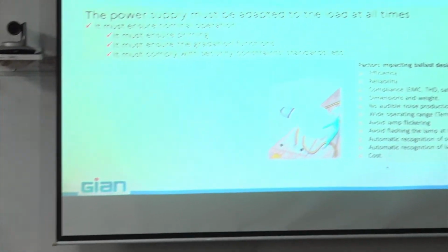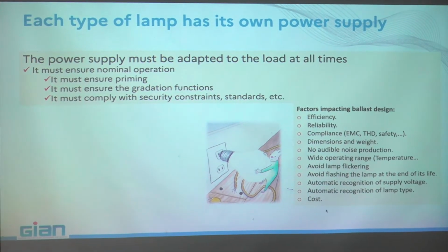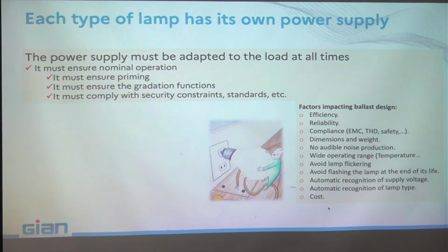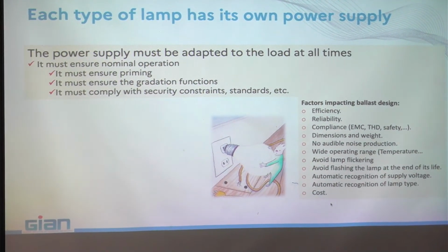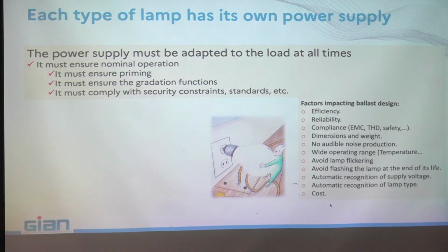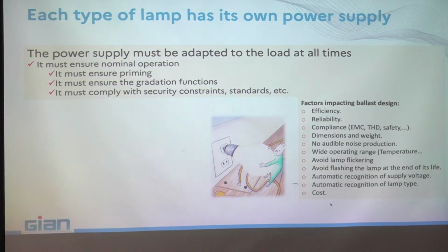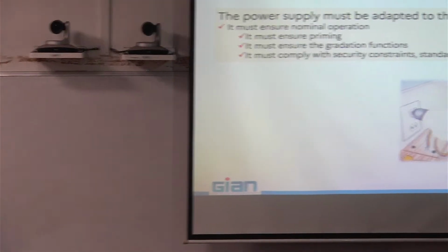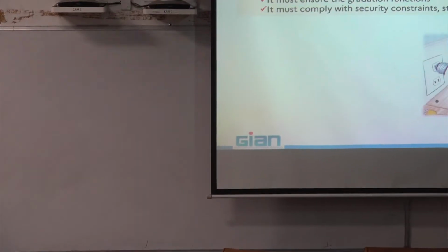In fact, normally each lamp technology has its own power supply, okay? And the power supply must be adapted to the load at all times, even if you have transients, or during the warm-up of the lamps, for example, or when you switch on the lamp. The driver normally has to be well adapted to follow all those transients. It must ensure the nominal operation of the lamp when the lamp is stabilized.